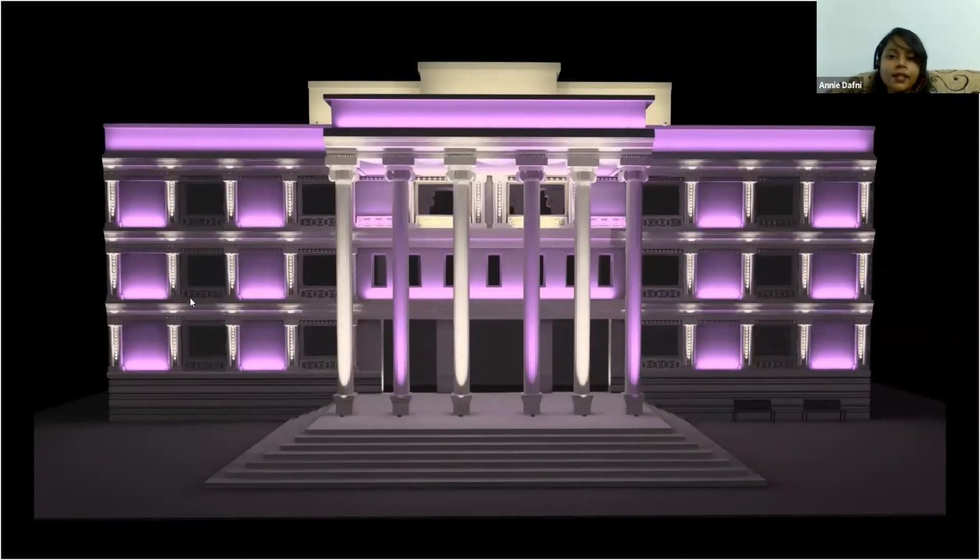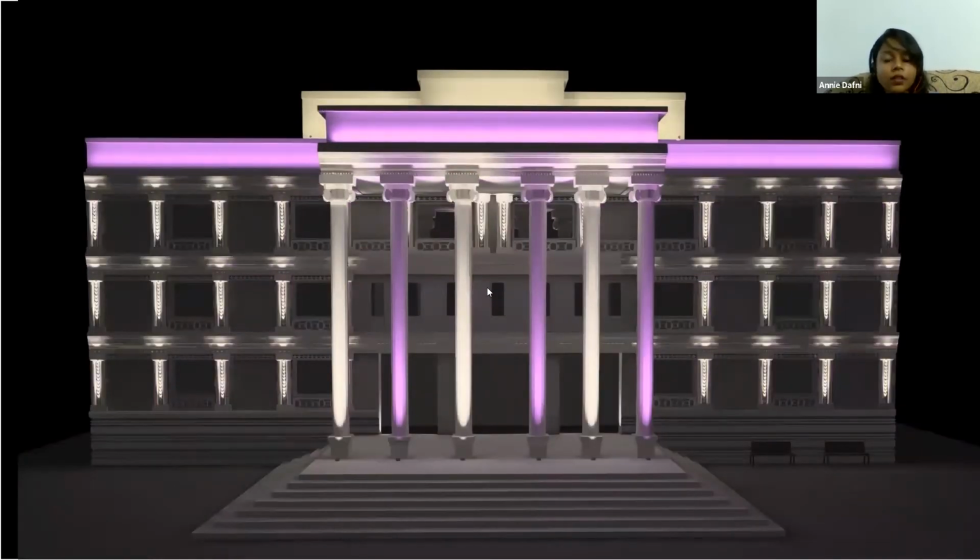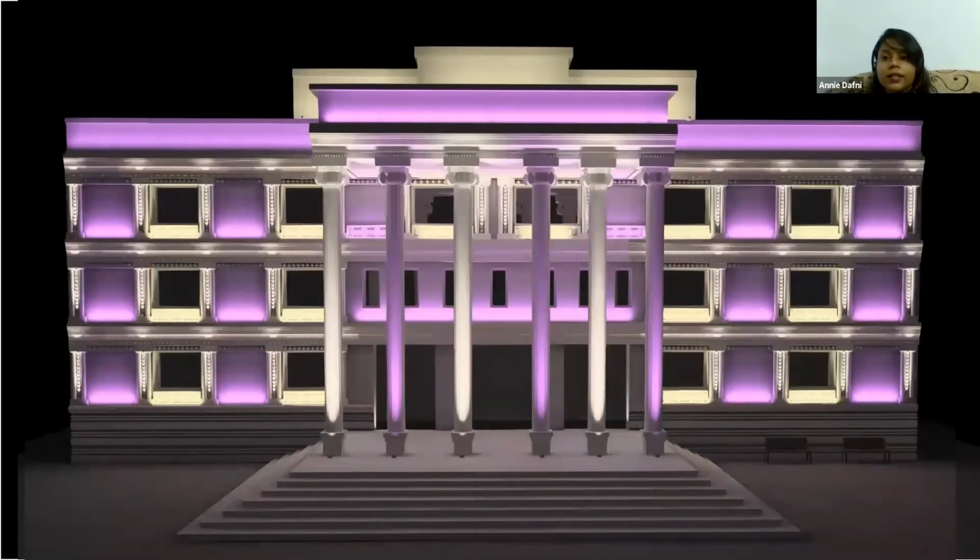Okay. And also, like I said, the concept of layered lighting also comes here, and you can play with a lot of scenes. So in this example, we've turned off all the lighting of the windows, and we're just highlighting the pillars and the solid portions of the facade. And then you can further create another layer by just turning off all the grazers and just turning on the washes and the in-ground fixtures with the crown lighting. And then you can create a layer where all the layers are on. So this basically gives the building a new look every time you create a different layer, and that advantage is present in the focal lighting technique.